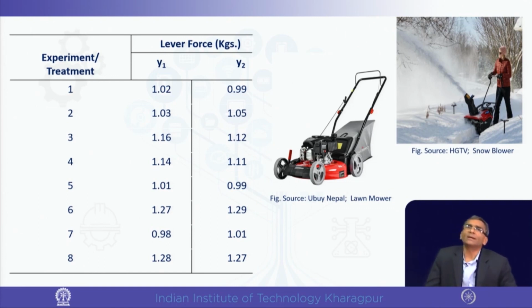With this we run the experiment. I said that there are 7 factors already in component and there are 2 levels. So, as we discussed earlier, it will be L8, the orthogonal array. L8 means there will be 8 treatment conditions, but here we could have just y1, so why have we taken y2? Because often it is found that a single value may be erroneous. If 2 values are not close, then we can investigate if anything has gone wrong.